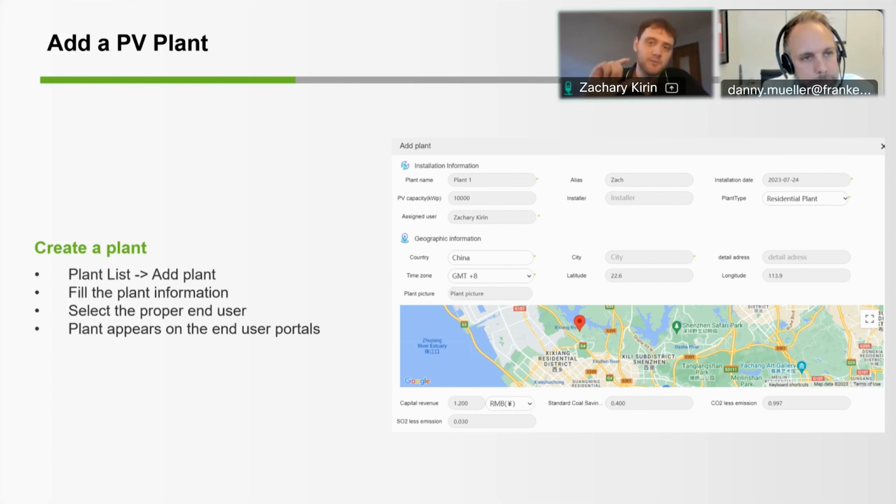Sure. Yes. The most important thing is the warranty should start at the date of interconnection. The very first time the system is turned on and starts to produce power and feed to the grid, this is when the inverter warranty will start. The date of interconnection is something that I would put here.